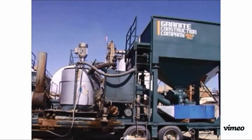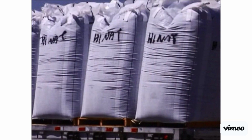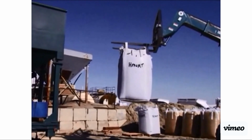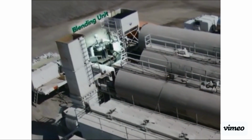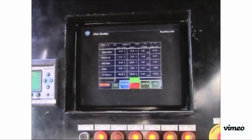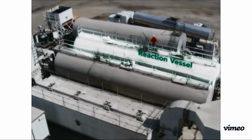The blending unit is where crumb rubber is blended with the elevated hot PG binder. The crumb rubber arrives on-site in 2,000-pound super sacks. The sacks are emptied into a hopper. The PG binder is simultaneously metered into the blending unit. The proportions of the RAC binder components are metered by a control panel based upon the binder design. Once thoroughly blended, these materials are then pumped into the reaction vessel.